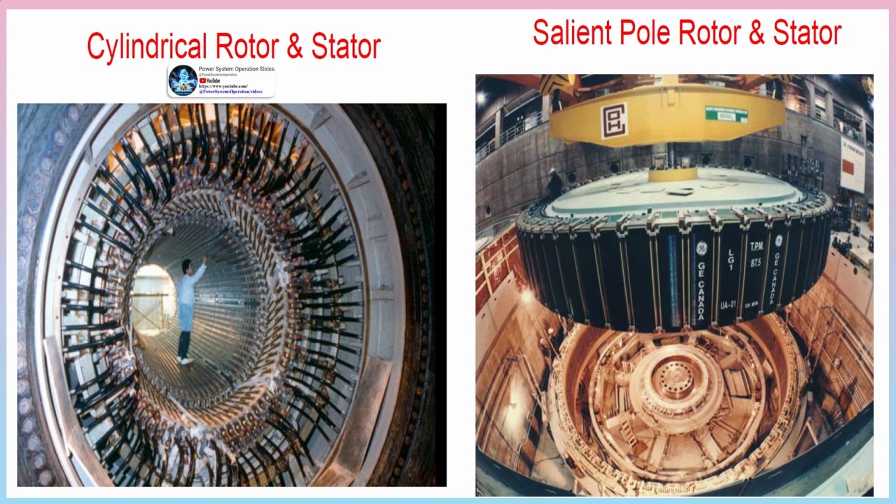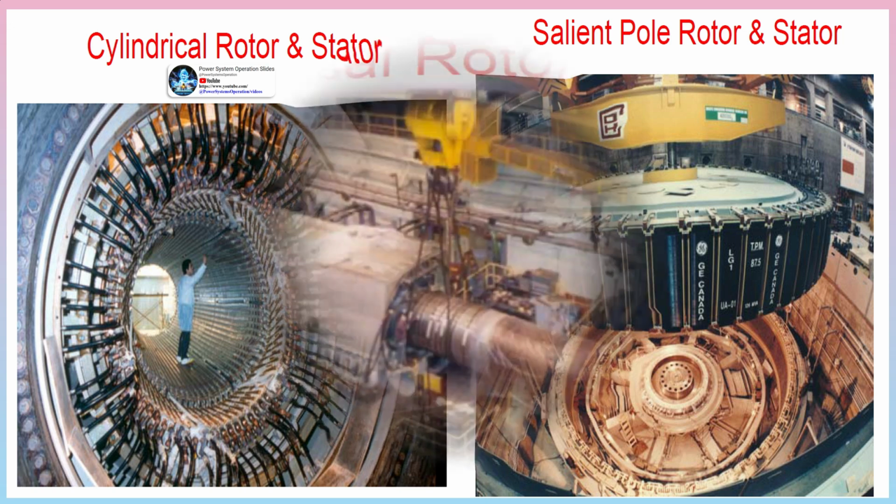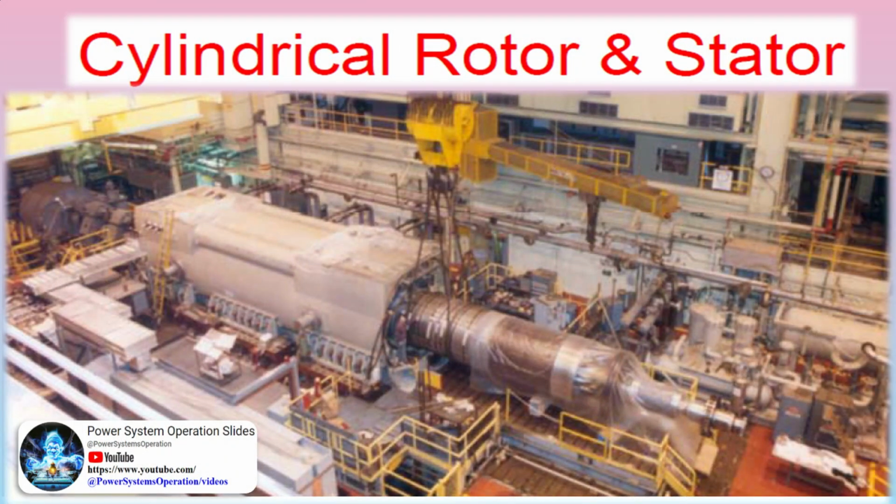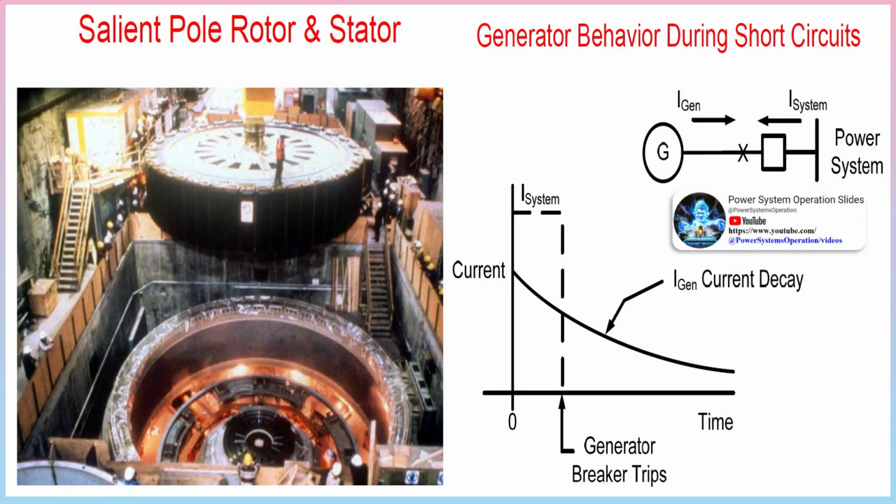Generators can face internal or external faults. Since generators are connected to electrical power systems, any fault in the system must be quickly cleared from the generator to prevent permanent damage. Generators can have many types of faults, so multiple protective schemes are used. These schemes include both discriminative and non-discriminative types. Coordinating systems and settings is crucial to ensure sensitive and selective generator protection.